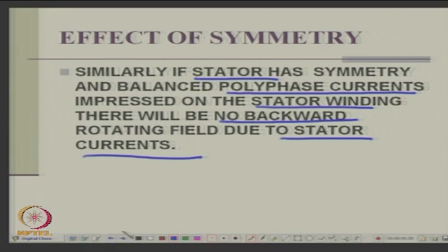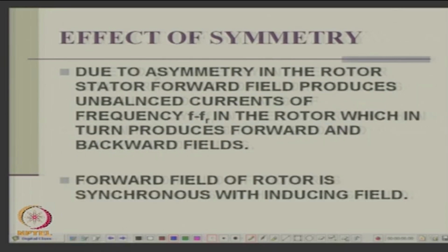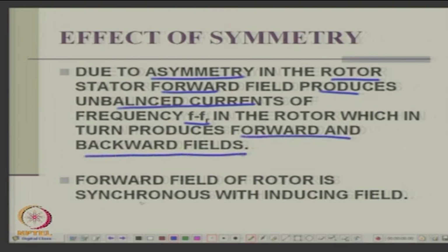The stator forward field produces unbalanced currents in the rotor of frequency F minus Fr, which will produce forward and backward fields. The forward field of the rotor is synchronous with the inducing field, there is no problem.